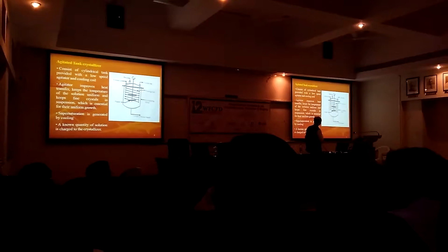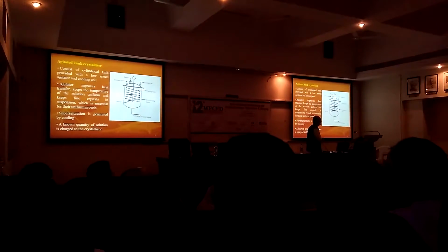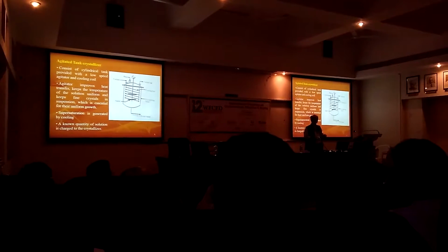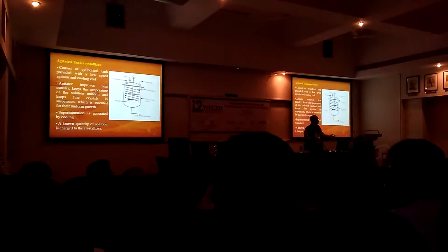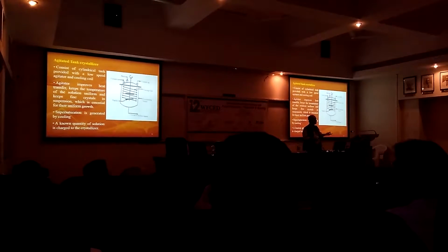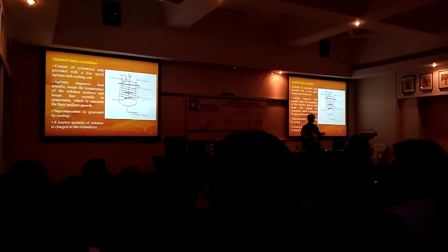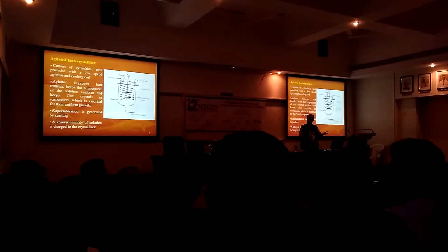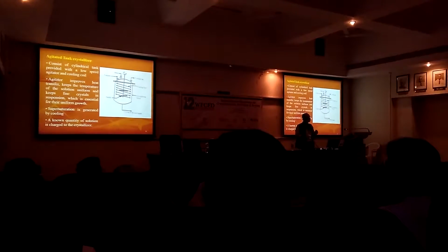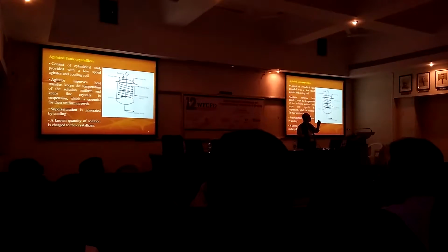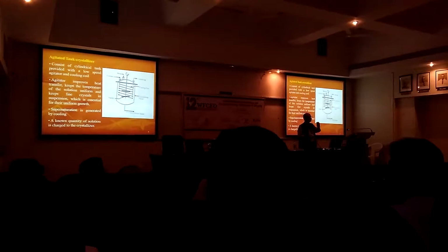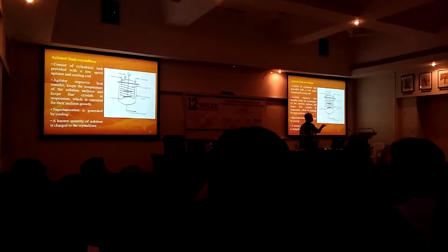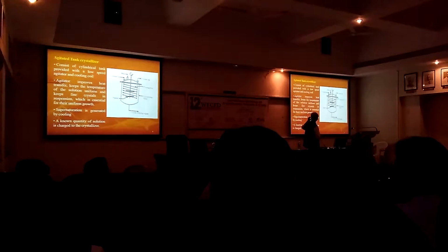You require material to be kept in suspension, and the crystallization process as such is exothermic. So you need to have a mechanism by which you can remove the heat when you want to carry out a cooling type of crystallizer. When you want to carry out an evaporative type of crystallizer, you are necessarily required to supply the latent heat of evaporation of the solvent.